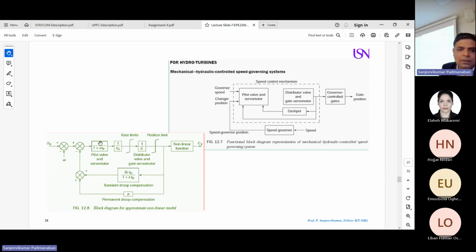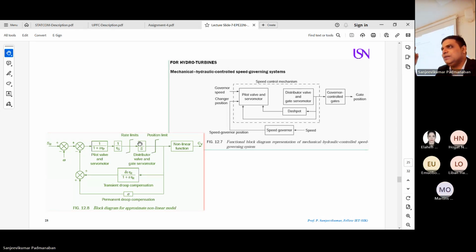So first order system. Then this is integrated again, 1 by tau G. So here it should be, yes, it's not required. Usually when you have a gain with a limiter, obviously 1 by s is presumed integrated. It's clear to you? So if you want more precise, you can put it, yes, it's not a problem. Then here, what is the difference? This integrator has a time constant of 1. Its time constant is 1. It doesn't have any other value.